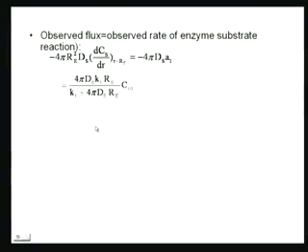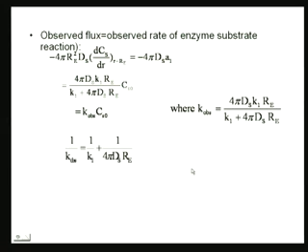Now, if you look at this, we can take an inverse of this. So I can write it as K observed times Cs naught. What would my 1 over K observed be? So, you take the inverse of this. Do you see what I am trying to approach? So, 1 over K observed equals 1 over K1 plus 1 over 4 pi Ds Re. Now, 1 over K1 is which resistance? Reaction resistance for the simple reaction, and 1 over 4 pi Ds Re is a mass transfer resistance. So, this is one of the cases.